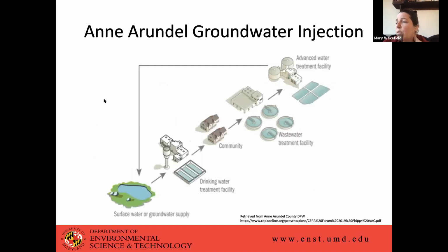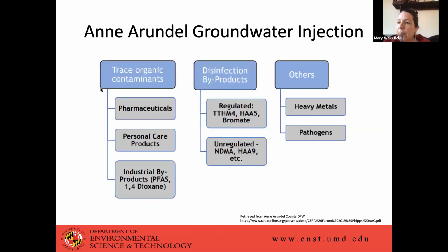So what they are proposing and what they are working their way through right now is going through your treatment facility into your wastewater facility, and then having advanced water treatment that will then be directly put back into the aquifers underneath the wastewater treatment plant. That means that the aquifers that you are withdrawing from for your agricultural purposes will not end up affecting the overall depth of your aquifer, and you are less likely to result with compaction.